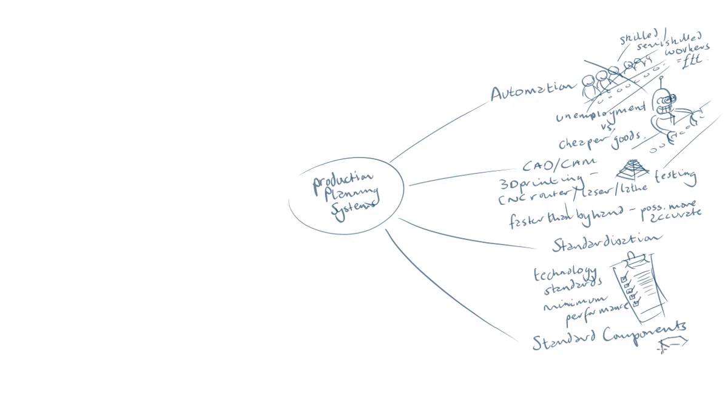Standard components, on the other hand, are the parts which are made by a specialist. So for example, nuts and bolts, or zips on a jacket. Whenever a designer is designing, they always bear in mind standard components, because this is much less expensive than designing and manufacturing bespoke parts from scratch. So if they were to design a chair, for example, they would design with certain types of bolts in mind. The issue with standard components is a quality assurance one. They have to make sure that the quality of the component coming in is good enough for their product.